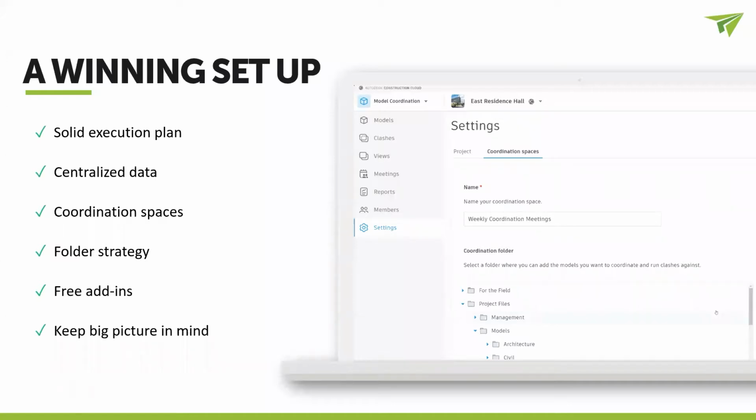Great. Thanks, Lisa. So what does winning with models look like? The first thing to understand is that there has to be a solid execution plan in place. It's got to be established at the very beginning of the design process, and it should be maintained, possibly updated, and followed all the way through the completion of the project into the handover. It needs to include any owner requirements, workflows, project-specific objectives, software tools, BIM uses, process mapping, and most importantly, the level of development, so that everyone's on the same page of how far they should take their scope of work throughout the process.